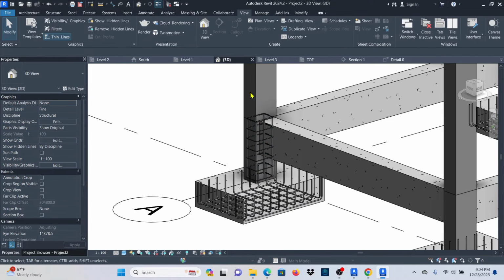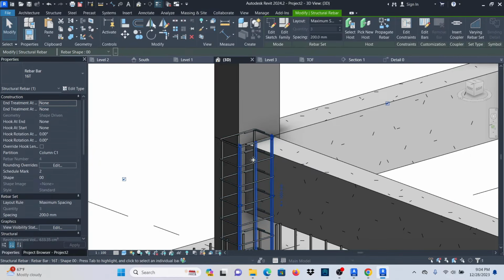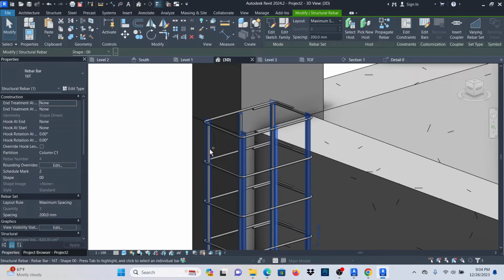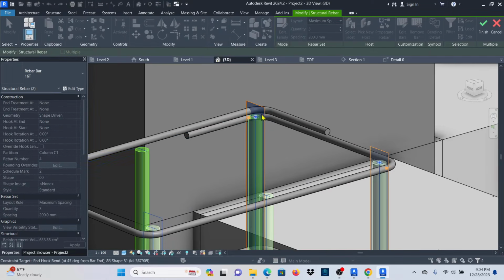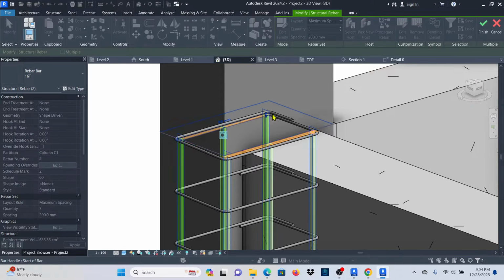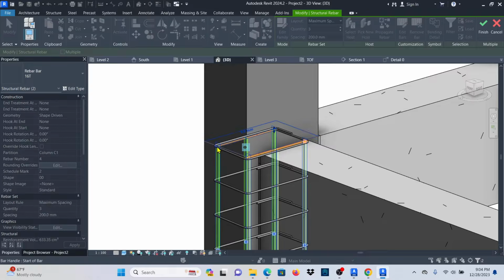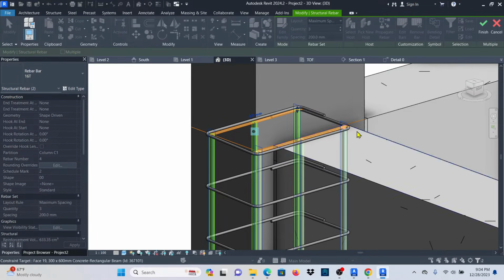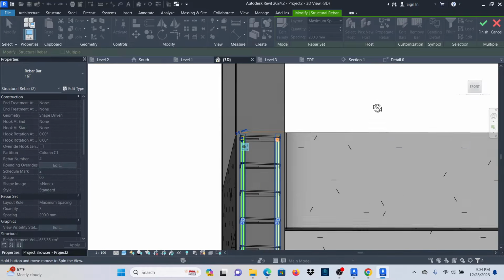do some starter bars on this column up there, and I'll use 600. So I'll select on this one and also hold control, select on this one. I'll go to edit constraints, then I'll just pick the top one here. Okay, I think all the bars, there's that one here. And now what I'll do is I just want to pick also the top of that column.